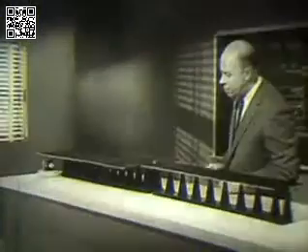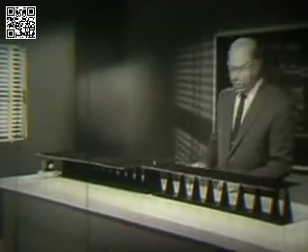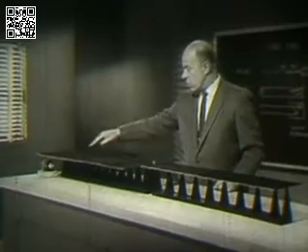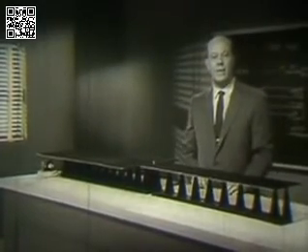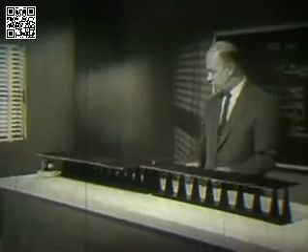At this point, where the two central wires are clamped together with this little clamp, there is an abrupt discontinuity in the impedance of the transmission path. A wave traveling slow along this medium will suddenly speed up when it crosses over into this one. This behavior is similar to what happens to a beam of light when it emerges from glass into air.